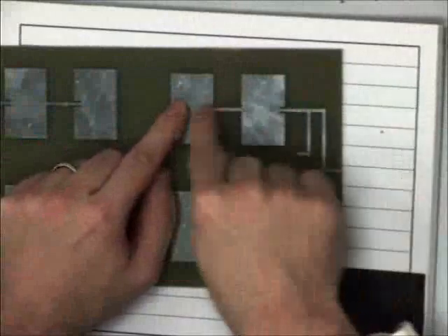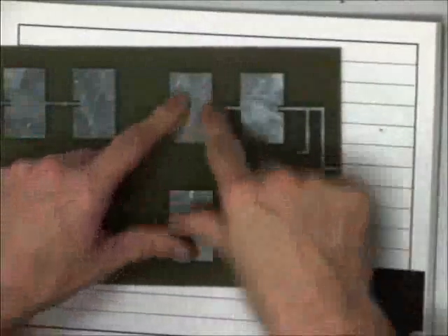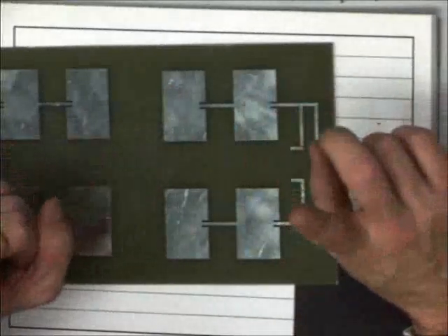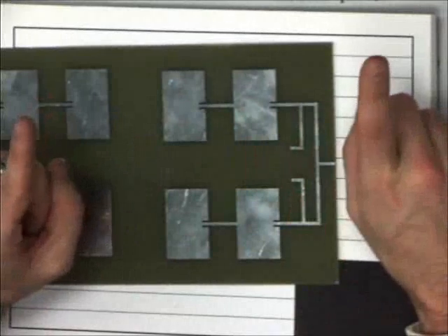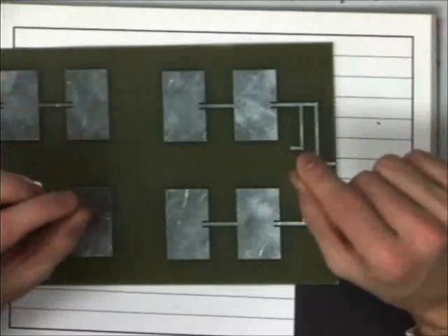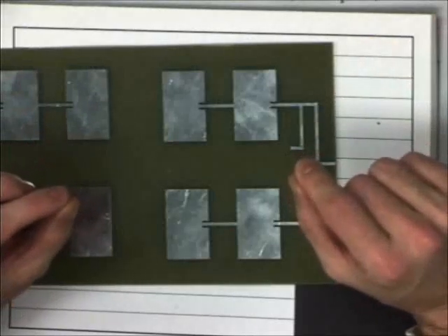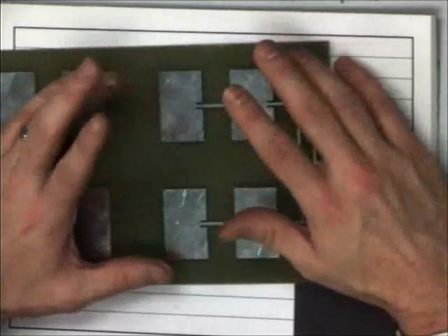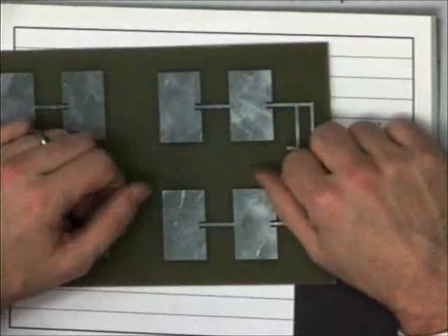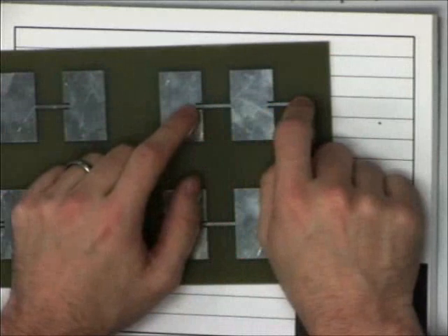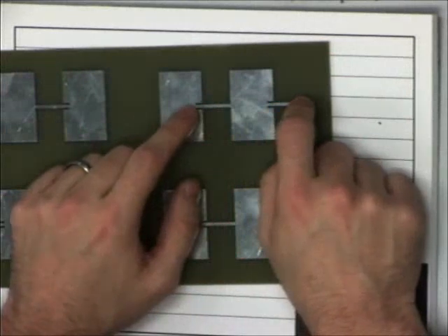So we have a transmission line, a 50 ohm line, terminated in a resistance here. And actually, it's a complicated network of these radiating structures. As a result, what you design is not necessarily what you get. You try to design something, and the reality never quite matches your simulated design software for this patch antenna. Maybe the impedance has an imaginary value, or the trace widths when you implemented them on a printed circuit board, or the fiberglass wasn't quite epsilon r equal to 4.0, or was inhomogeneous, or something like that.